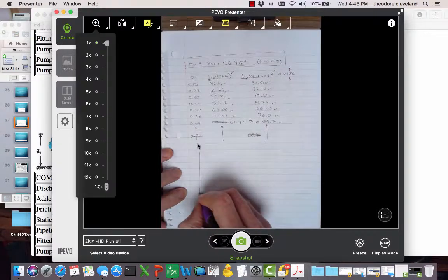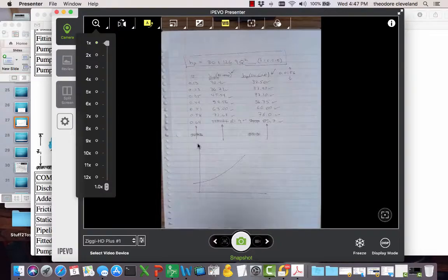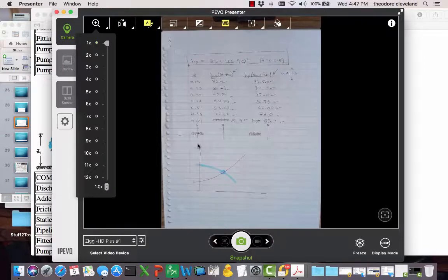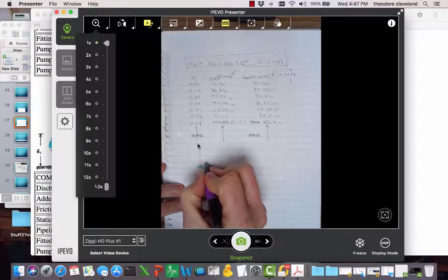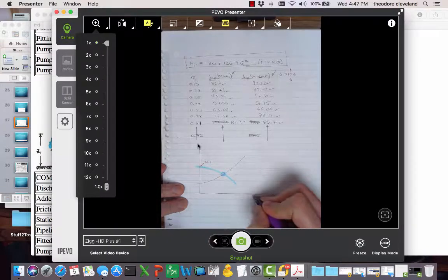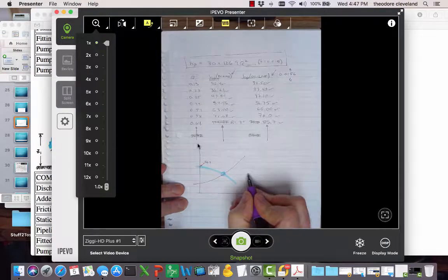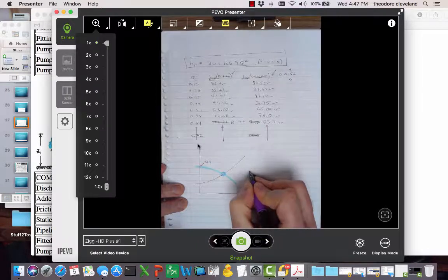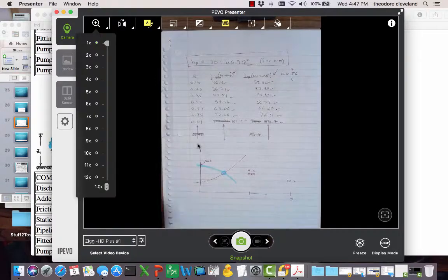So if we were to plot that, let's see, 30, our plot looks like that. Then when we go to an actual pump, we would intersect it and we get that point. So let's suppose we have an actual pump that has shut off of 56.2 meters, and at 1, 2 is, oh, it's not that bad, 41.2 and 38.7. So let's say that's the pump that we get from a manufacturer.